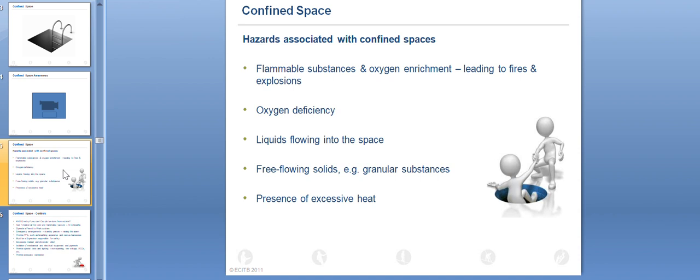Wherever we have to work in a confined space, we must take care of proper access and egress. A gas test should be done: hydrogen sulfide less than 10, oxygen at or above 19.5, and other gases such as carbon dioxide or other combustible gases should be zero. You should know how to use the gas tester, and a permit is also required for the confined space. Without the permit, entry is not allowed.